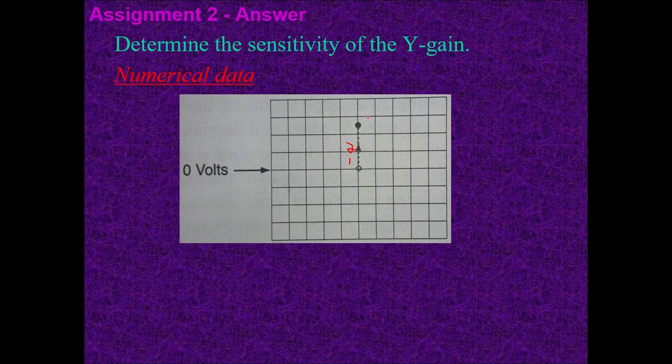So our accuracy here is only 1 division, but how do you then get these other small values? You cannot say a third of the division unless you have subdivided it much smaller. So anything in between here is basically a half. It's assumed to be a half. So basically you'll have here a half of a division, or 0.5.